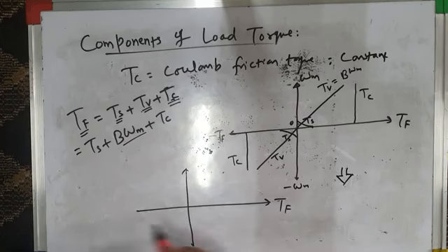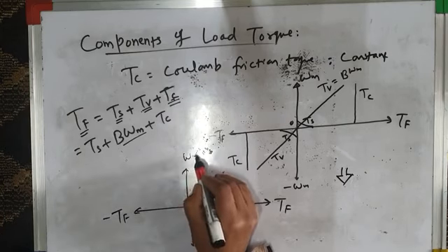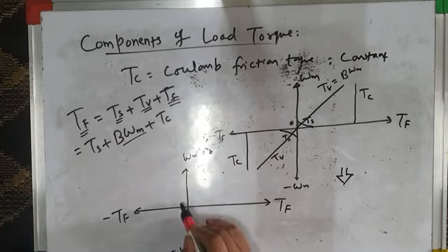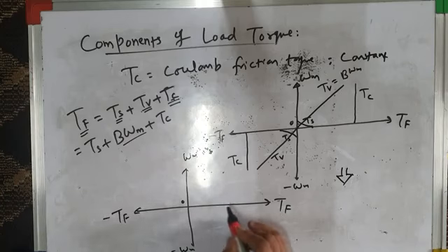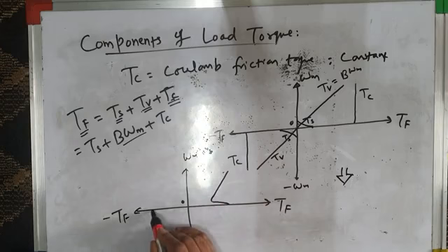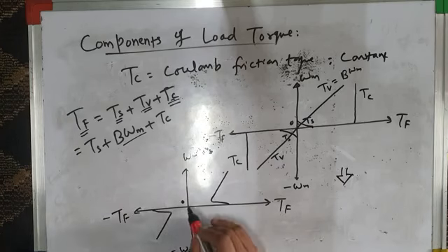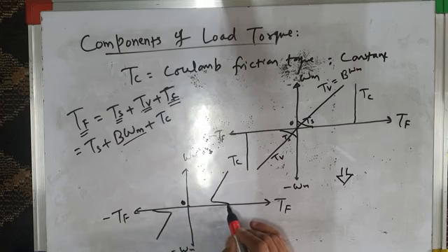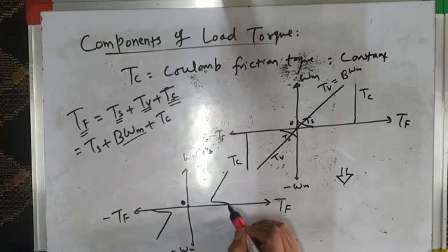This is the friction torque, speed. It will become something like this. Similarly, something like this. When the motor and its driven load, I mean when the drive is at standstill, it's not running, then it has a certain amount of friction torque, which is, again, I call it static torque or stiction.